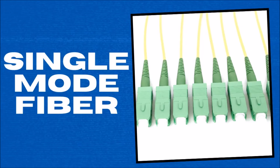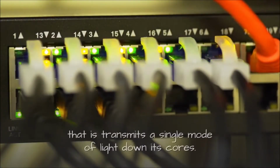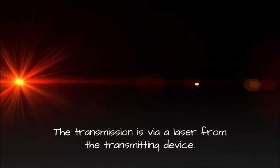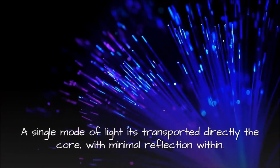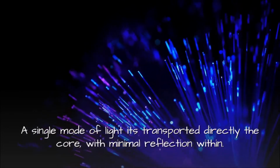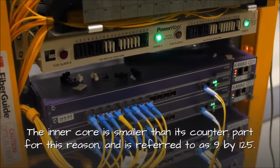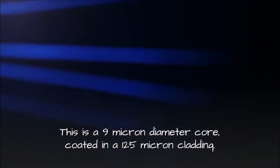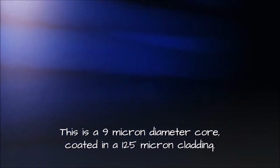Single-mode fiber. The terminology of a single-mode fiber comes from the fact that it transmits a single mode of light down its cores. The transmission is via a laser from the transmitting device. A single mode of light is transported directly down the core, with minimal reflection within. The inner core is smaller than its counterpart for this reason, and is referred to as 9 by 125. This is a 9 micron diameter core, coated in a 125 micron cladding.